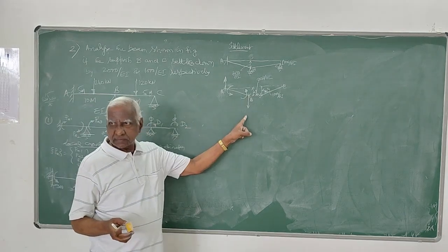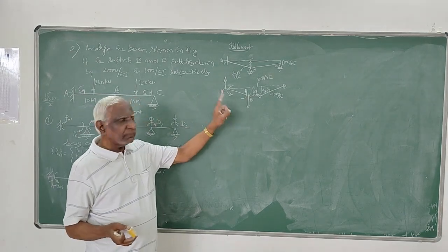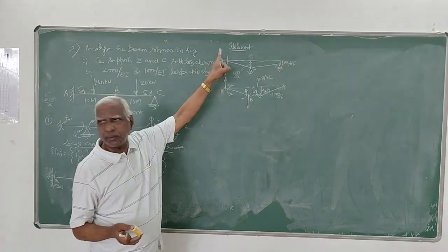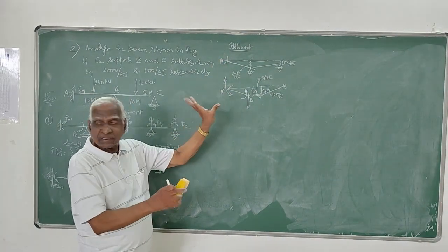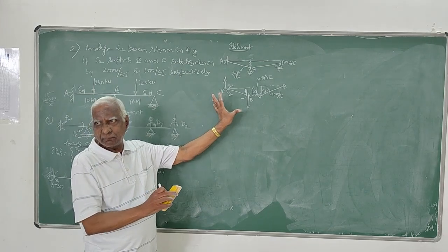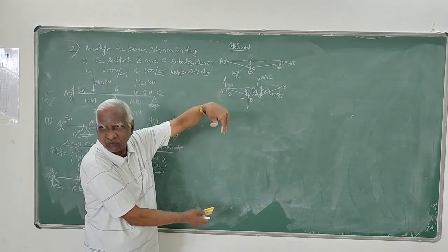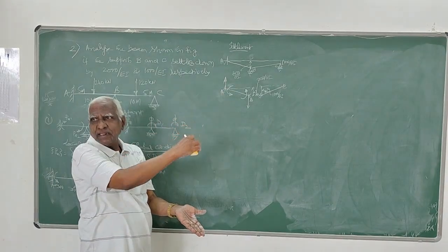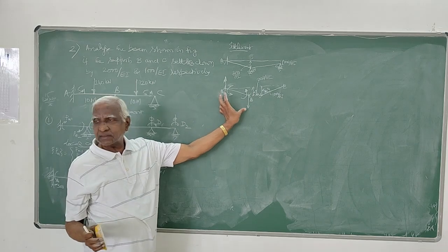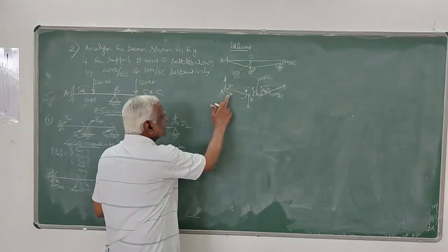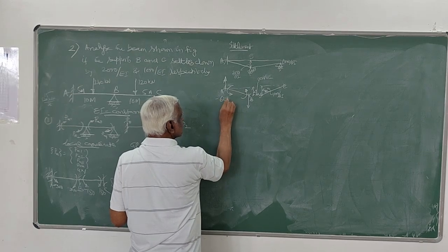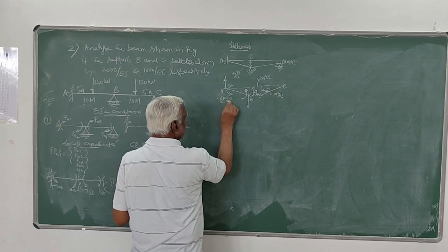To keep this in equilibrium, an equal and opposite force. So this force should be equal to this. This force again is not in equilibrium. It gives a moment now in the clockwise direction, so this has to be resisted in anti-clockwise. So now this is in equilibrium, and this anti-clockwise moment is minus 6 EI delta by L square.